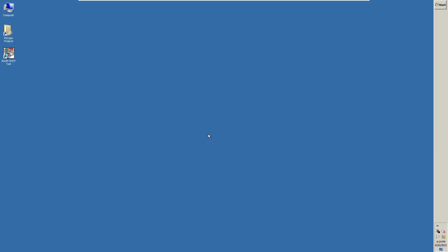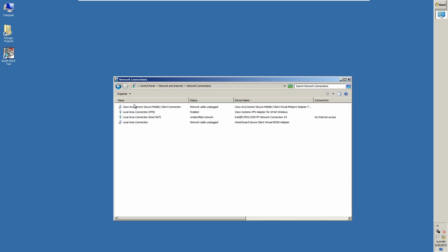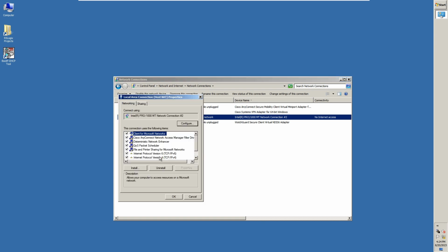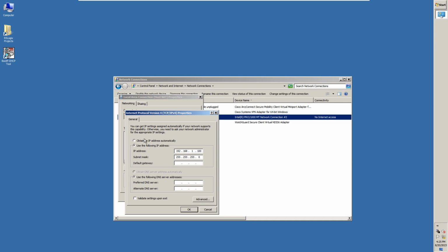Once you are physically connected to your PLC processor, you want to go ahead and get access. First thing you're going to want to do is go to your network configuration. Now in this image I am running Windows 7, an older version of Windows, so your Windows layout will look different. I'm going to go to your network configuration settings, your network adapter, your Internet Protocol version 4, TCP/IP v4, and make sure that you have your network address set to a static IP address.